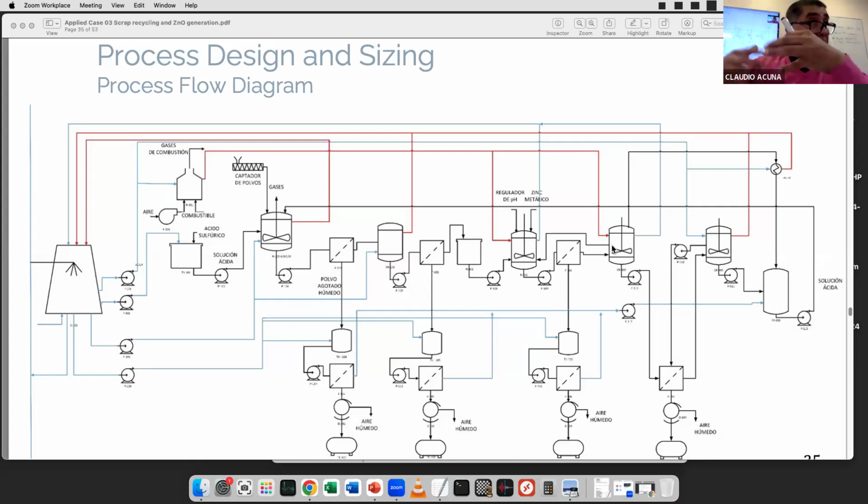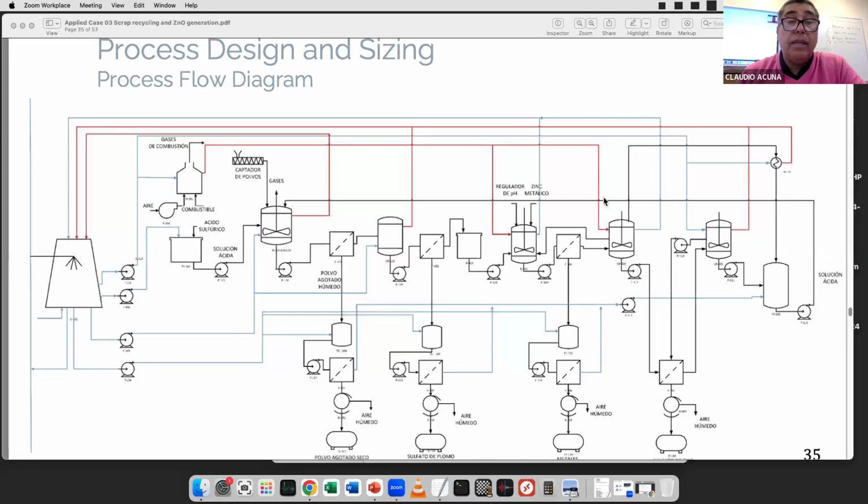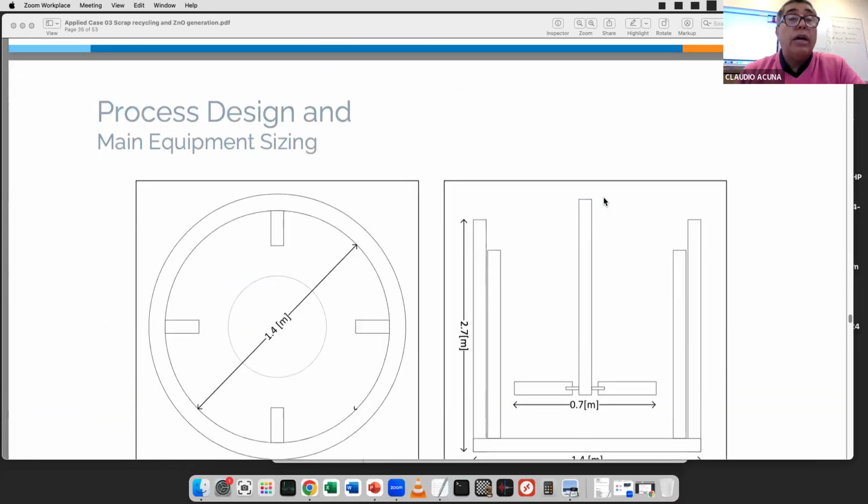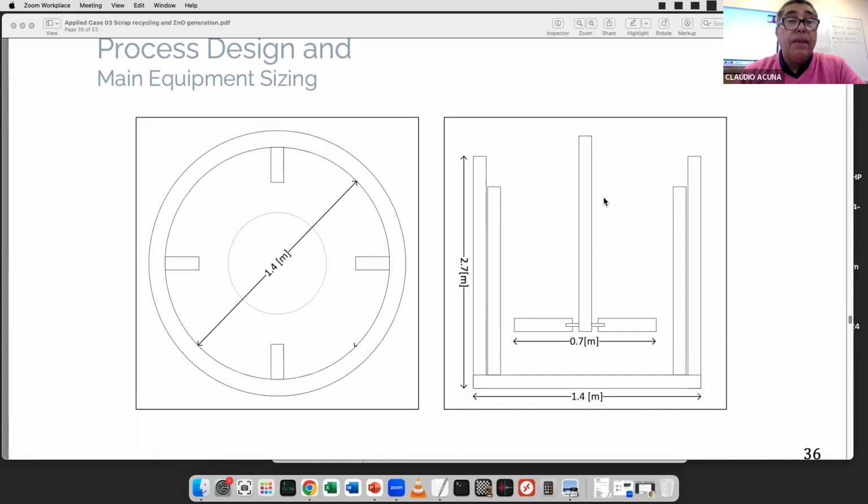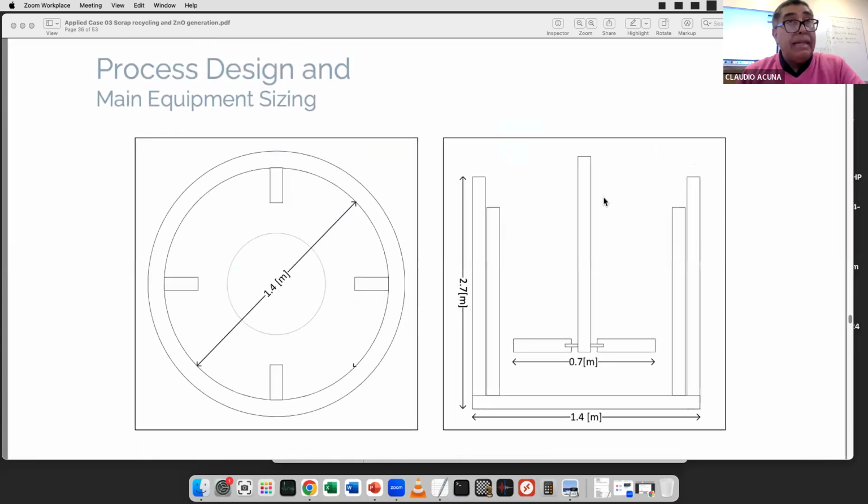Okay, because they're practical. Construction, in the case of pharmaceuticals, is 5 times more expensive than traditional, because it requires some specific things, for example. But those things, I think you saw in the process design. Okay, now the size of the equipment. In this case it's batch, so the kinetic is the same. We just scale up the impeller with tip speed.